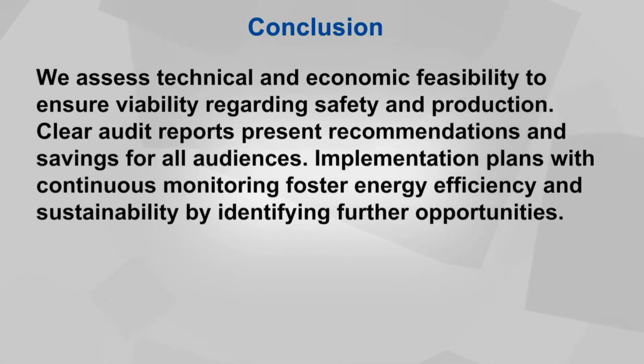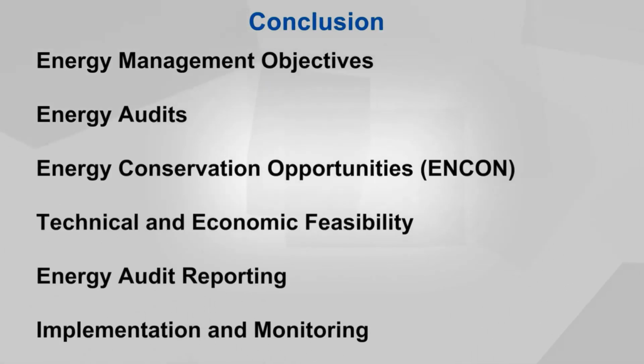The main themes covered broadly throughout this module, energy management and audit, include: number one, objective. Energy management focuses on minimizing cost and environmental impacts while optimizing energy use to enhance profitability and competitive advantage. Energy audits are essential for identifying energy wastage and improvement opportunities. They are categorized into preliminary, targeted, and detailed audits, each with a specific focus and depth of analysis.